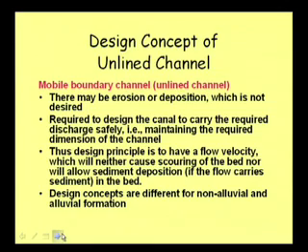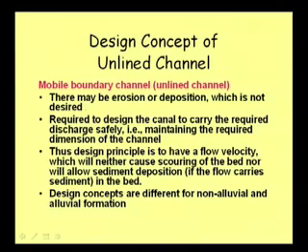When we talk about design concept of unlined channel, the entire concept is different. Here we are not talking about best hydraulic section, or rather we can say that the most economic section is not the best hydraulic section here, because the entire concept is different. So, there may be erosion or deposition.